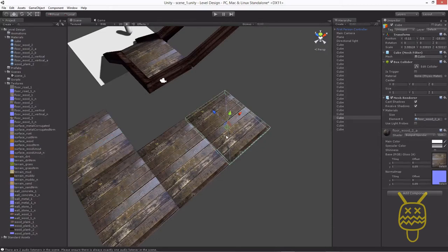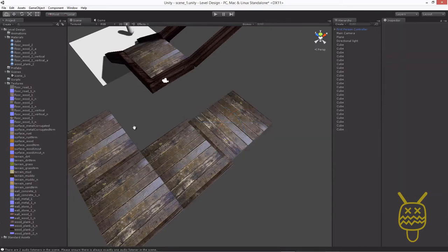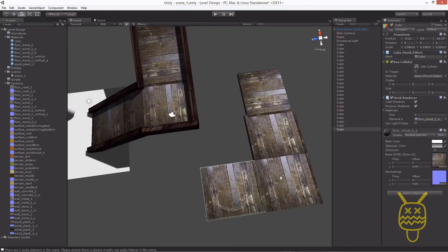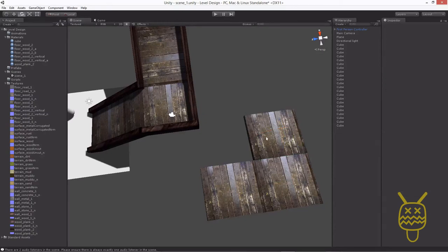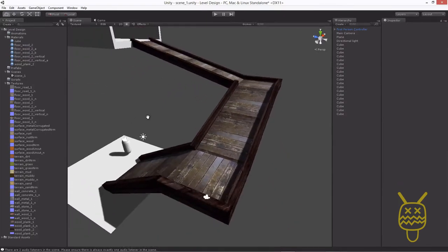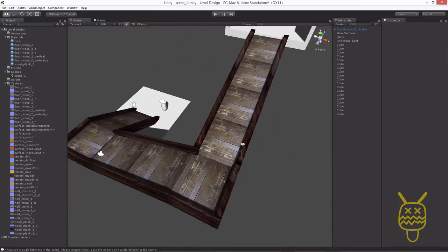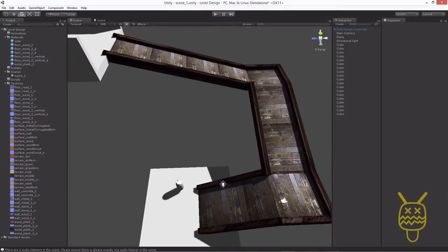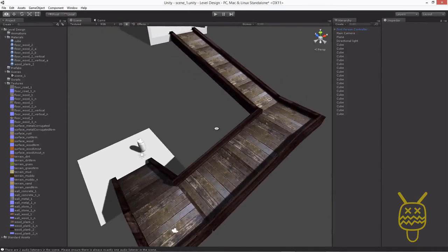And that way if I get to a spot like this and I was supposed to have it rotated, I could rotate it this way if it was a square. And then all of a sudden you don't have to worry about a different material. You're only having one render call for the material, but you're having more geometry in your scene. And if you have it modeled by an artist, they can deliberately make the UVs have multiple, so that rather than just being one long stretch, they'll cut it and then they'll flip their UVs across on each other.